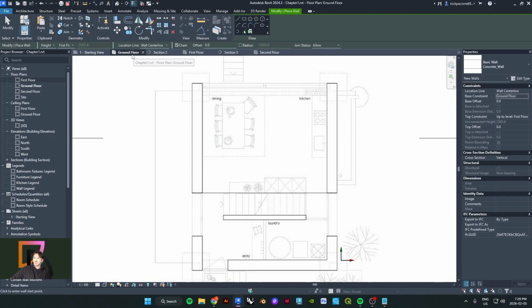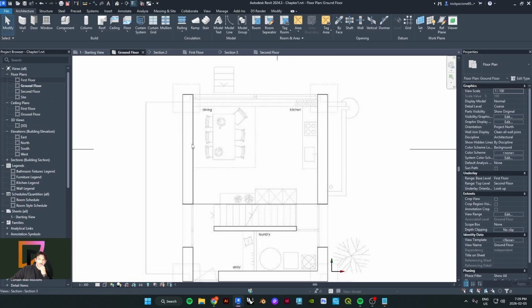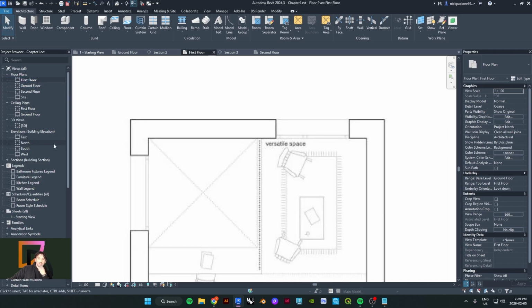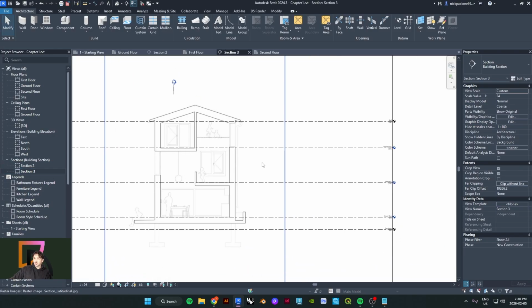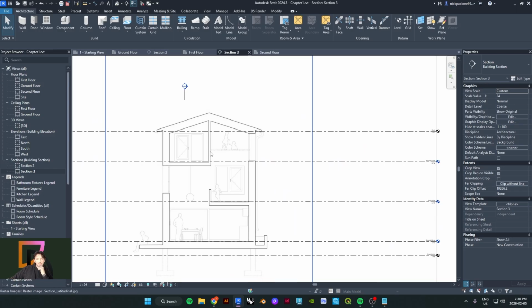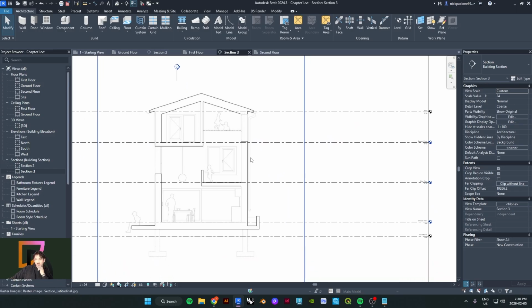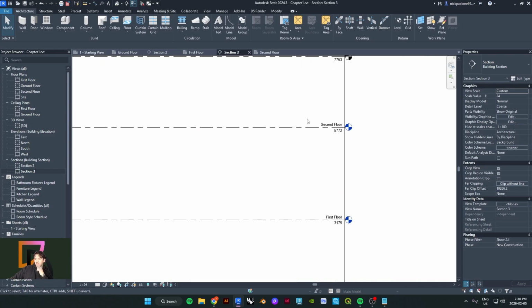So something I did early on, before I actually do this, I'll show you. What I did when I scaled the floor plans was I made the levels. So if you are working from the base file provided, and if you go into the section, I took the drawing of the section provided, and I basically created levels from this.